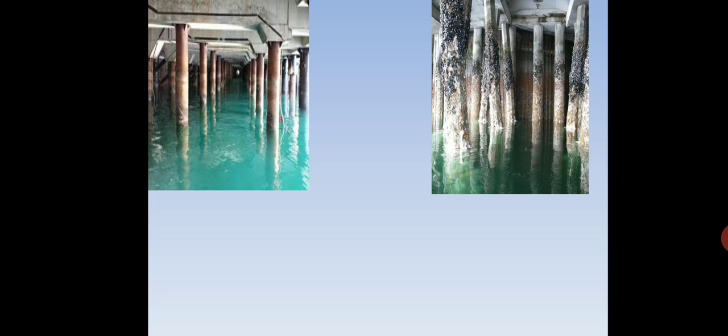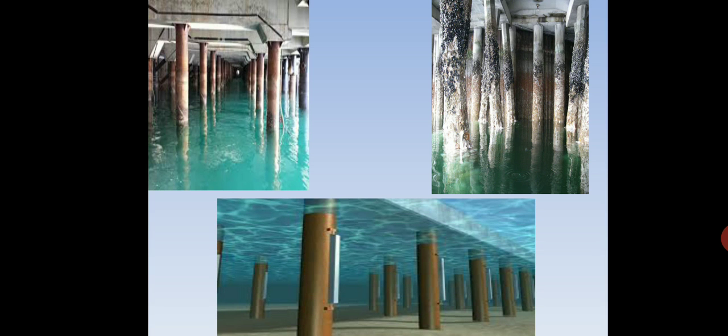So there will be huge loss. To avoid that, as you can see in this picture, once again the underground, this is an iron pillar, and one more active metal, it could be magnesium, zinc, any metal, is connected to this iron pillar. So it acts as anode, and it will undergo corrosion first, hence it protects the iron pillar. In this way, the sacrificial anode method works.